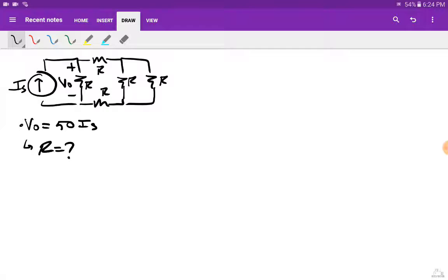I actually recommend, if you see a circuit, the KVL and KCL is most often the last thing that you want to try to do to solve it. Not always, but most often that's probably the last thing you want to try. The first thing you want to try is looking for current and voltage dividers. If you can't see that, then try to reduce the circuit.